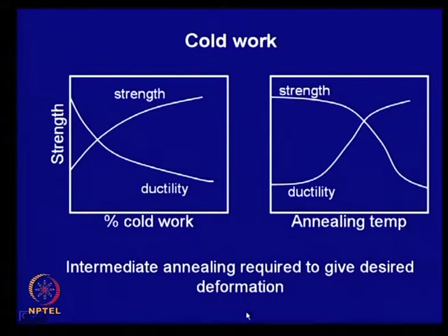Now, what happens when you cold work a material? If you cold work, your strength increases. As you give more and more cold work, your strength increases and its ductility decreases with percentage of cold work.